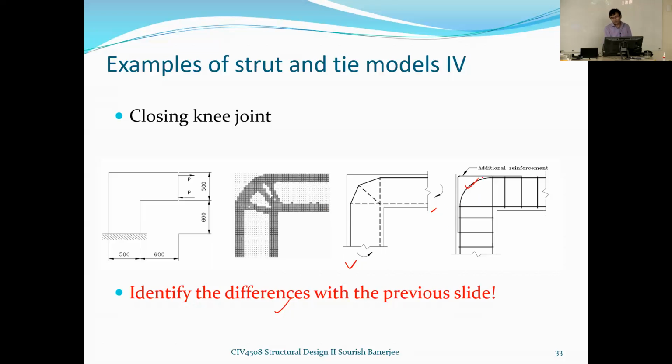So the top reinforcement is actually bent and then going down, or the column reinforcement is going like that. You can think of it either way. But because there is a gap in this case, we can provide what is called additional or skin reinforcement. Because if there's too much gap between these two areas, then you have to provide that. Otherwise, you get cracks in this region.